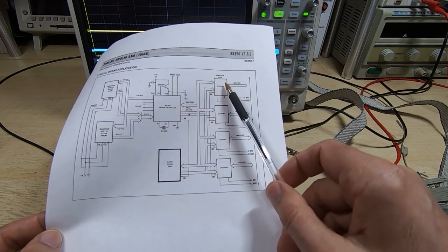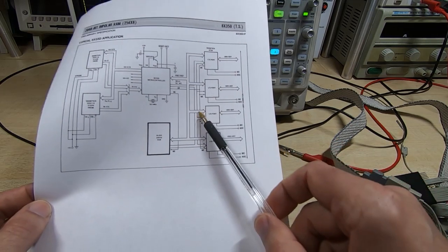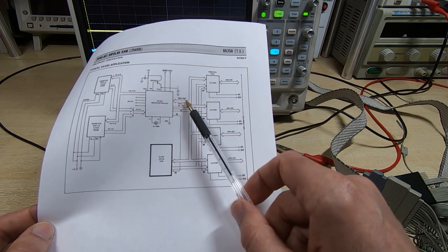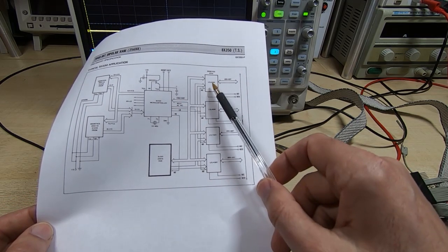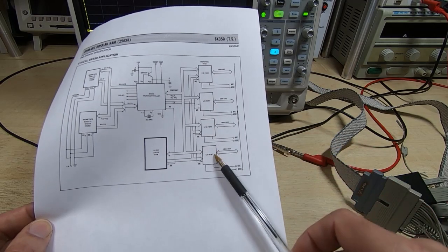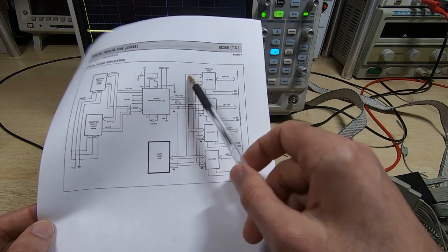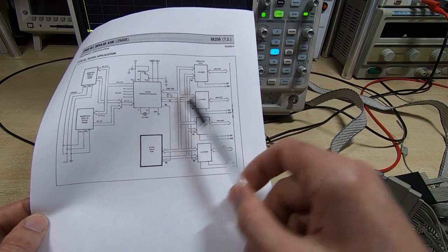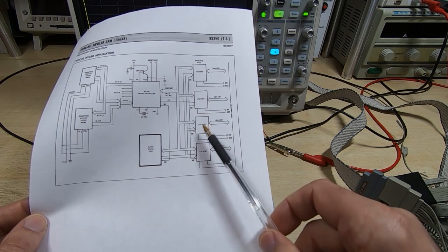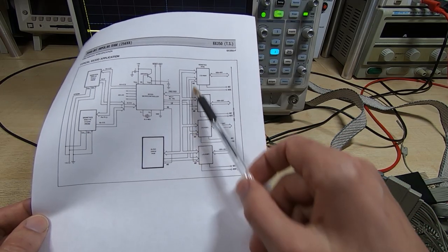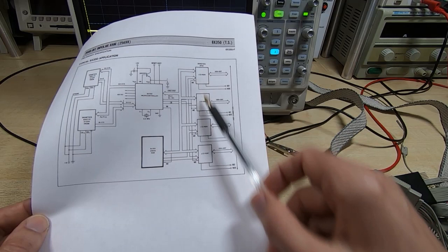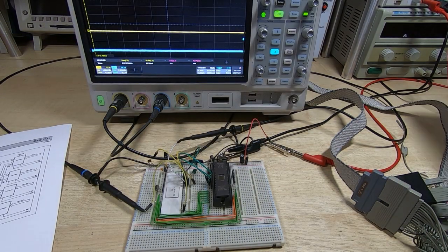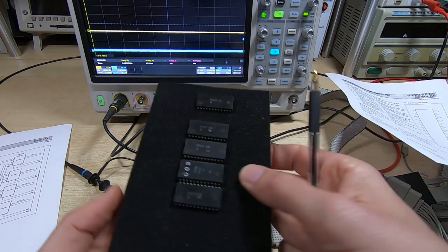So if you notice here, all the ports are connected to a common bus. It's an 8-bit bus, and the question there, of course, is, well, how does the system know how to address each of these ports? Because if they're all connected to the same one and there is no logic to select them, there's no separate logic to control them, all the chip enable lines are common, how does the system know which of the ports it's writing to? And the answer there is easiest to explain if we look at the devices themselves.